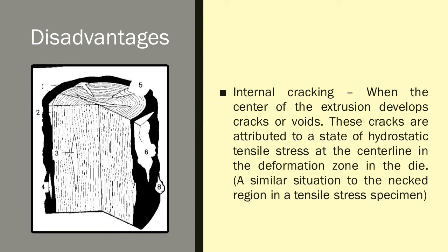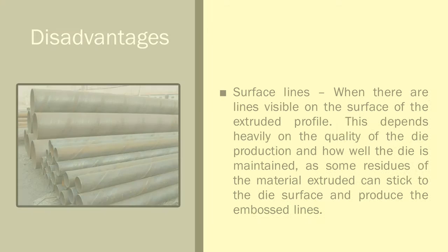Internal cracking. When the center of the extrusion develops cracks or voids, these cracks are attributed to a state of hydrostatic tensile stress at the center line in the deformation zone in the die. A similar situation to the necked region in a tensile test specimen.